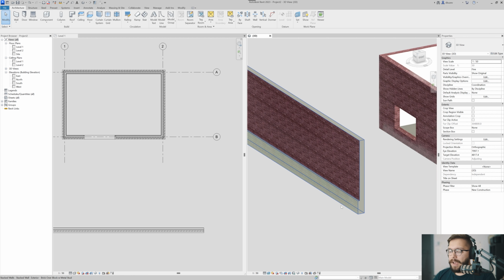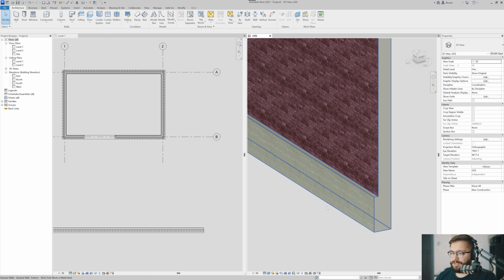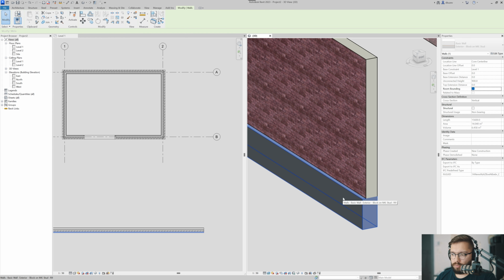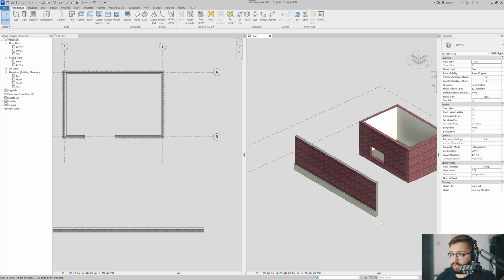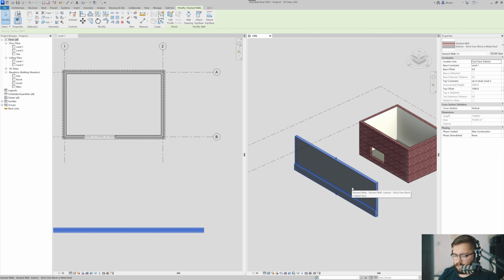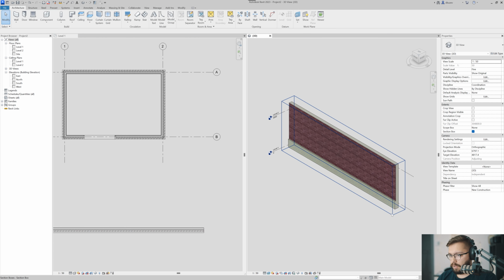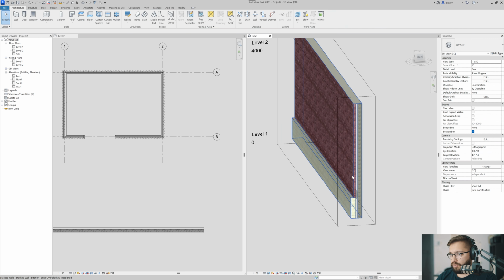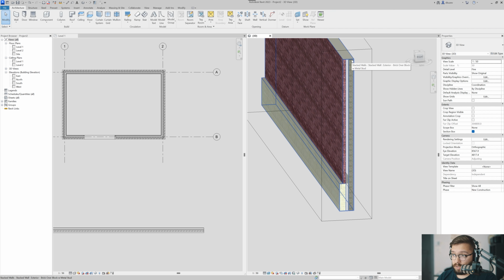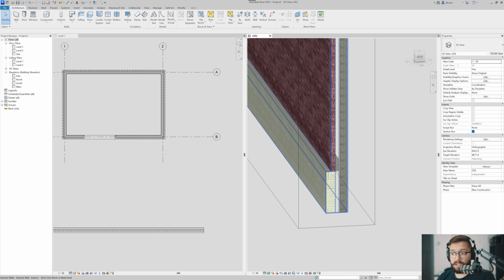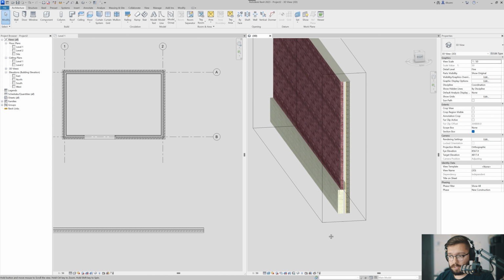This is it. So in this particular case, the default Revit one, they have this stone wall, and then they have this brick wall on top. So that makes perfect sense. If I select it and say BX, so I can create a box and cut through it, you'll see that I can see their composition, and it makes perfect sense. Whatever the stud or the concrete block is a continuous thing, the insulation as well, and they're just changing the finish on the outside, okay?